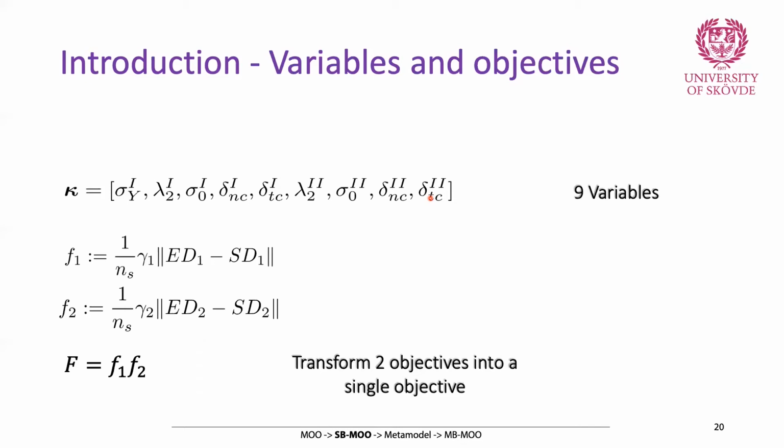So if you want to have the simulation as near as possible to the physical experiment, you have to reduce the error between the two plots, the two stress strain curves. So the objective here is to minimize the error between the two curves. ED shows the experimental curve, and ST shows the simulation curve. And as we said, 2 modes, the peel and shear mode, will dominate in adhesives. So we have 2 different plots, one stress strain curve for peel and one stress strain curve for shear. And we want to minimize the difference between these 2 stress curves from experiment and simulation.